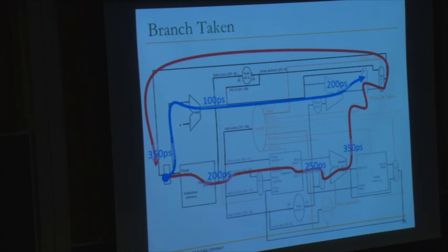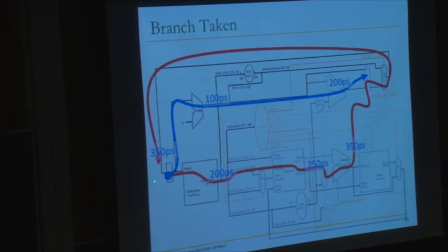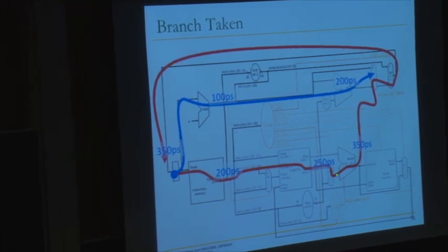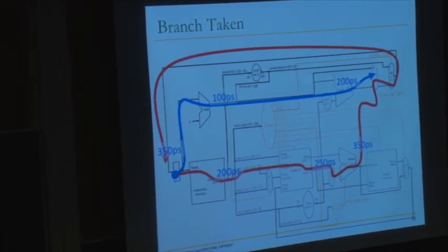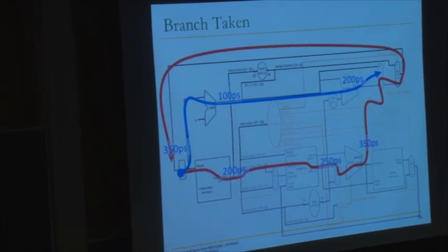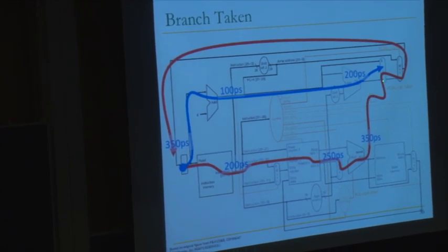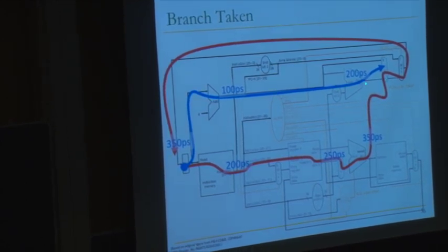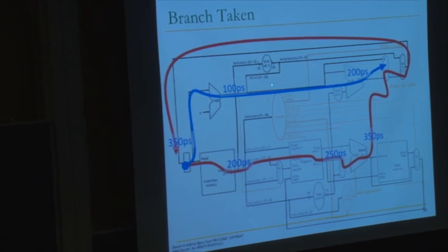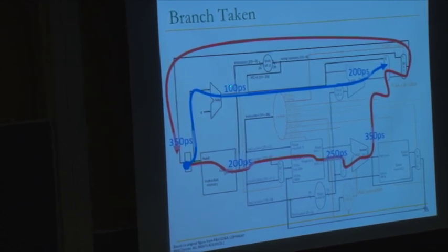But you also need to determine the branch condition, right? Whether or not the branch is taken. And that is determined through the register file. You need to read the registers. You need to compare the two registers, depending on the opcode. You do different comparisons. And based on the result of the comparison, then you choose either the output of this adder or PC plus 4, output of this adder.